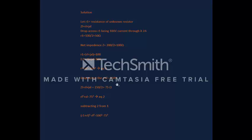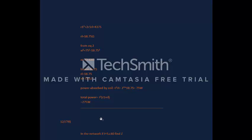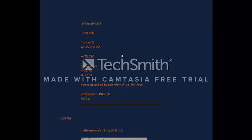The drop across the coil is equal to 150 volts. ZL is equal to RL plus jXL, which is 150 by 2, or 75 ohms. Also RL square plus XL square is equal to 75 square. Let's take this as equation 2. Subtracting equation 2 from 1, we get (R1 plus RL) whole square minus RL square is equal to 100 square minus 75 square. It turns out to be R1 square plus 2 R1 RL is equal to 4375, and RL turns out to be 18.75.